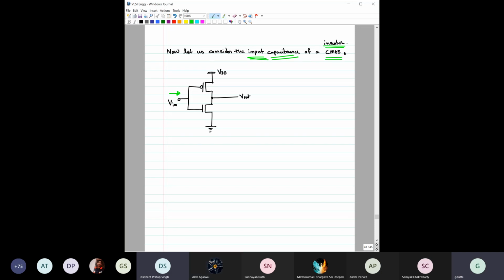It's not possible, right? Because we have seen the region of operation. So, it's not possible that both transistors are in triode for a CMOS inverter. So consider one saturation, one cutoff, then it is possible. So for cutoff, there will be a major part from the gate body capacitance for the cutoff transistor, and for the saturation part, we will have only the drain to body and source to body. So what do you think would be the total capacitance?